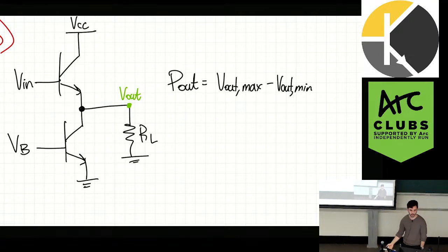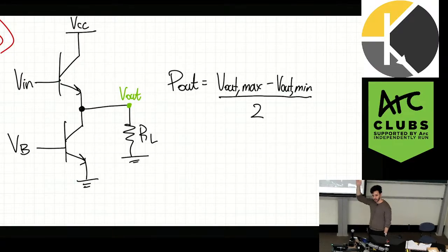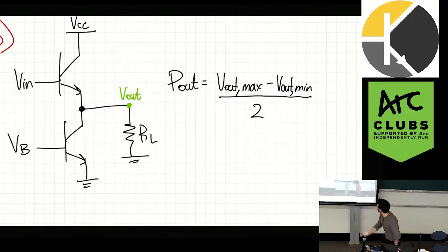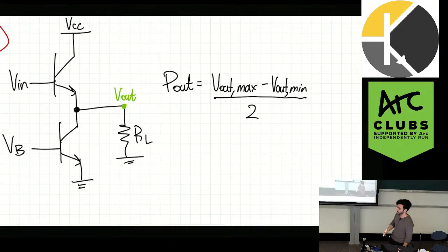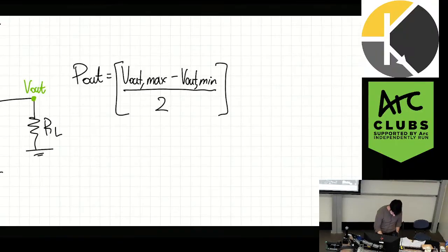Okay? So, because when we're thinking about power amplifiers, this is large signal analysis. So the voltage swings are large. So we need to think about what happens as it swings up and as it swings down across this resistor. Okay? And also because it's an AC wave, so we look at the maximum and the minimum point for power. So V out max squared times 1 on RL.